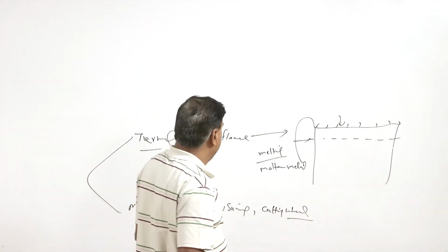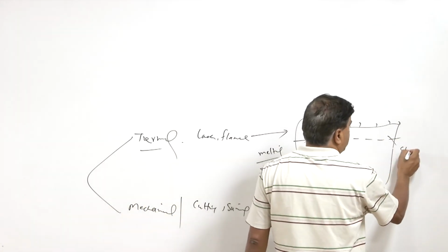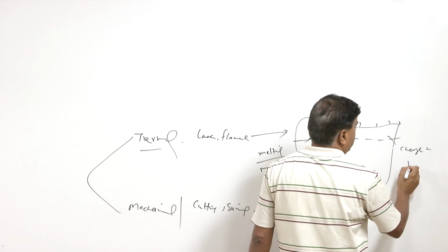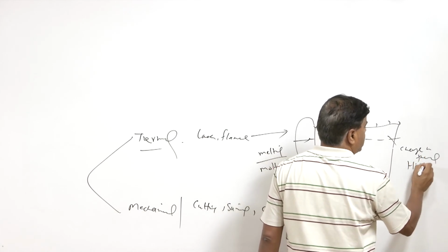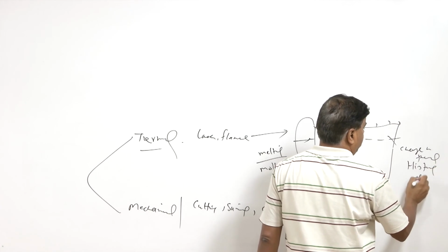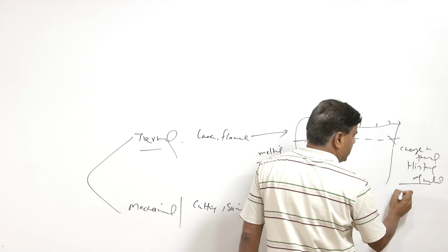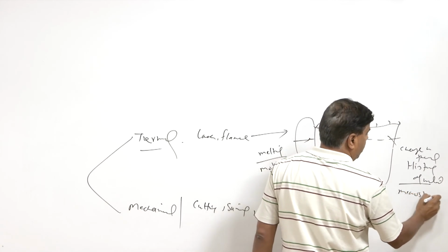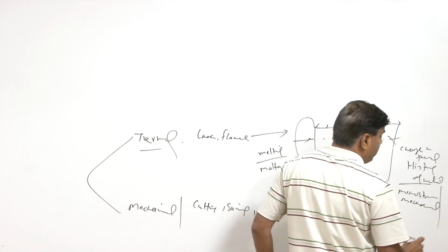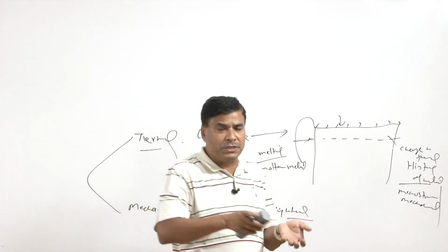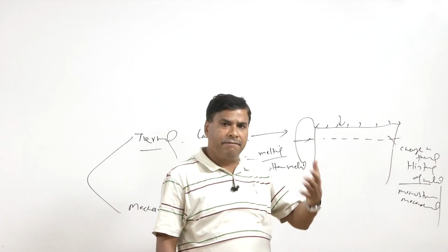This is one. And when thermal methods are applied, there is always a change in the thermal history of the metal. This change in thermal history leads to a change in microstructure, which can lead to a change in mechanical properties. This is more damaging, because we will have a sample whose properties, in terms of mechanical behavior or microstructure, have been modified.